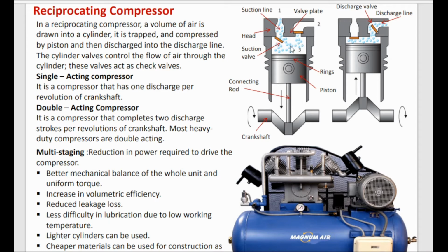And when the pressure is more than the pressure here, which is connected to the collecting tank, automatically this will get opened and the compressed fluid here will be moving or passing to the collecting tank. That is how it works.